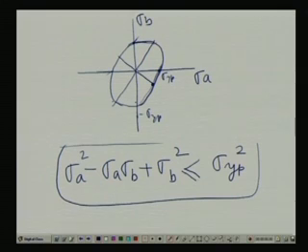Once again it will be just exactly dividing, and the coordinate of this point will be where sigma A equals minus sigma B. If you substitute, you will find this point coming out as 0.577 sigma yield point. You can verify this result.